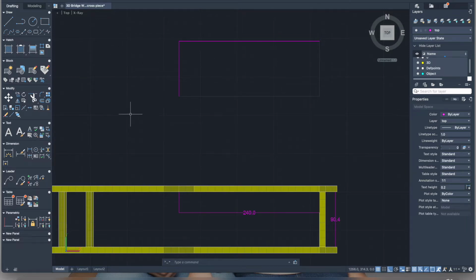And then what we want to do, a lot of you are doing smaller X's as opposed to going right across. So I'm going to do the more complex shape, because if you can do this, then you can do the easier version. Grab our line here, get our midpoint, come down, spacebar, spacebar again to reactivate the last command.